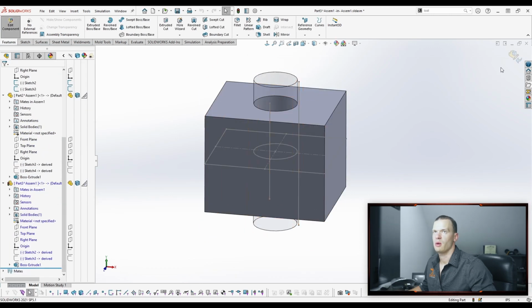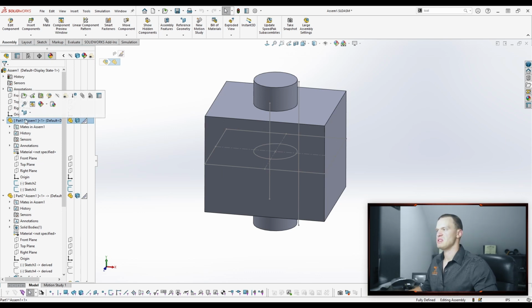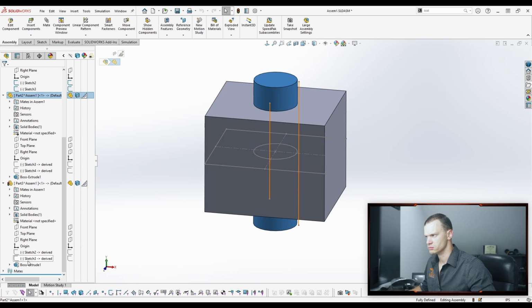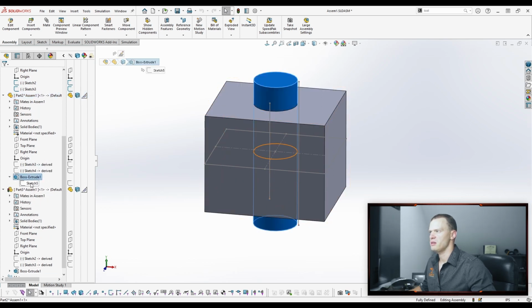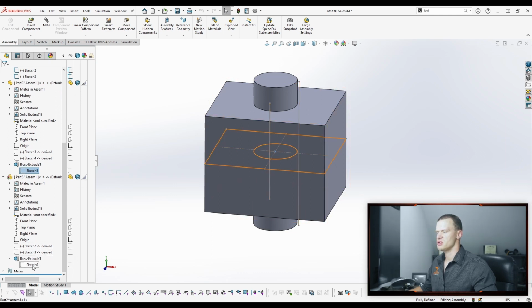So now we can kind of look at what we have, right? So we have our skeleton sketch part, which basically is the holding point for all of our sketches. And then we have these parts that we create from those sketches that we've derived in. And we can see that the features that we create and the reference sketches that we create as well don't have external links. See how they don't have those arrows, right? That's one good check. All of your features and all of your sketches should not have external links. The only external links should be in these derived sketch.